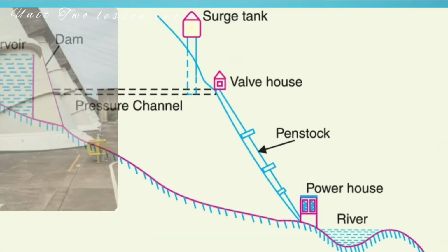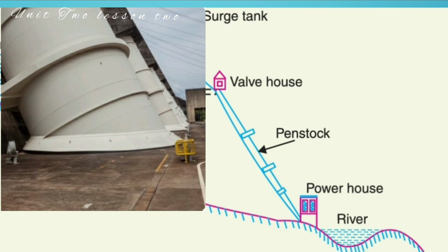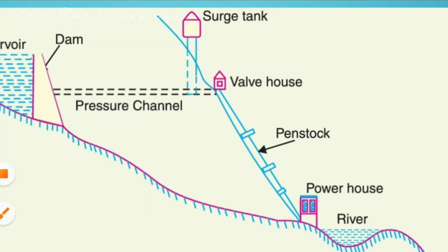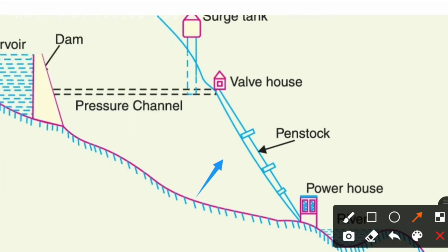Penstock. The penstock is simply the carrier of water to the turbine. It can be of open, closed, reinforced concrete, or steel type. Various devices such as automatic butterfly valve, air valve, and surge tank are provided for protection of the penstock. The automatic butterfly valve shuts off water through the penstock immediately. The air valve maintains the air pressure inside the penstock equal to the outside atmospheric pressure.